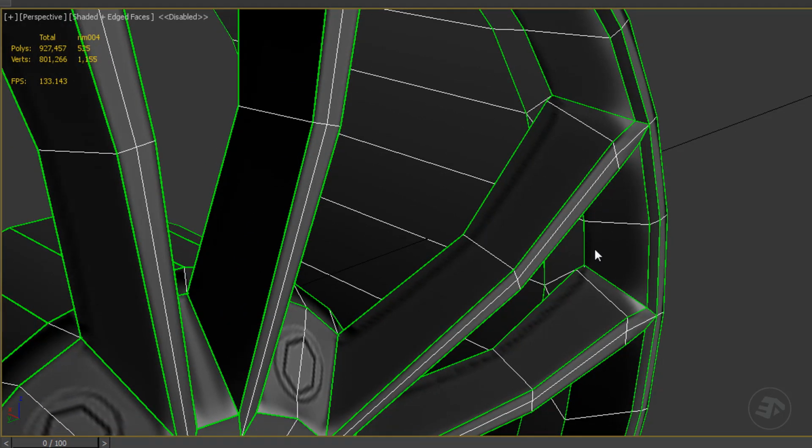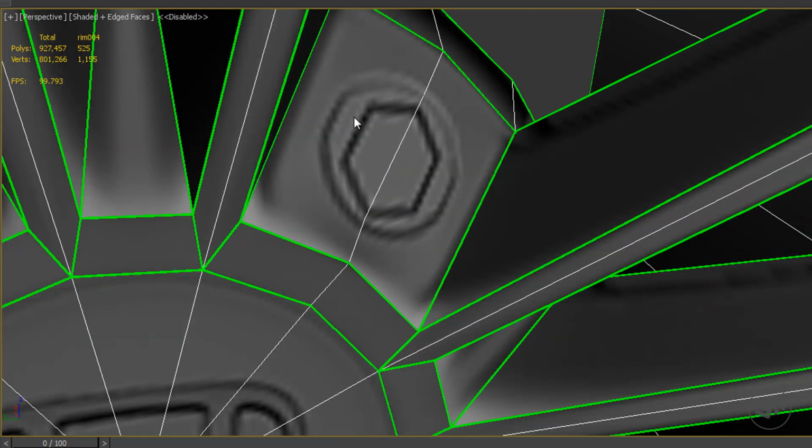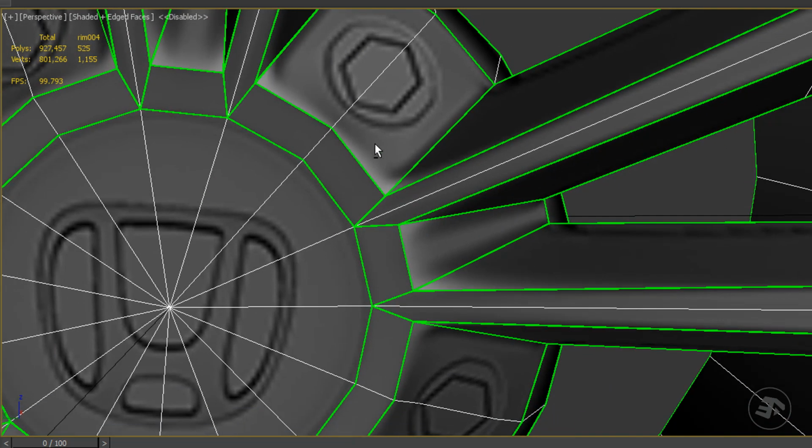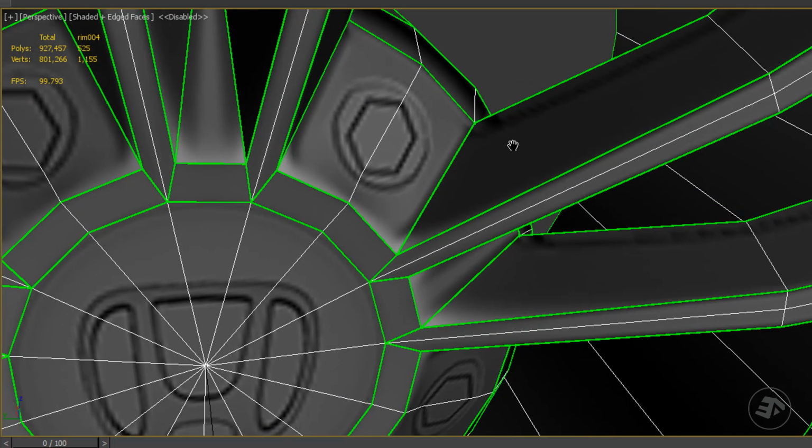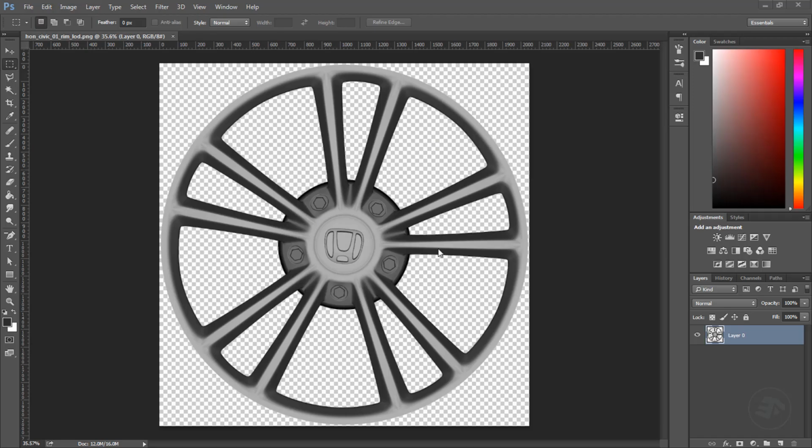You need to visually inspect the 3D model for any texturing distortion, such as the darker lines at the rim pillars' inner edges. We can fix this by editing the UV map. However, this is a texture problem, and the right decision, in this case, is to edit the texture itself. Our texture also has a lighter color in cavity areas, such as the bolt attachment holes, which definitely looks unbelievable. We need to give these areas a darker color in order to fake depth. We need to have the original bake map for this editing.